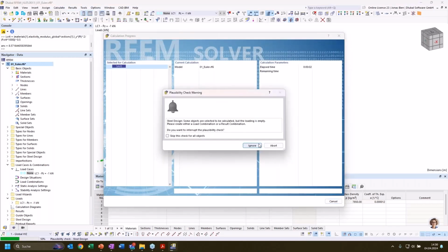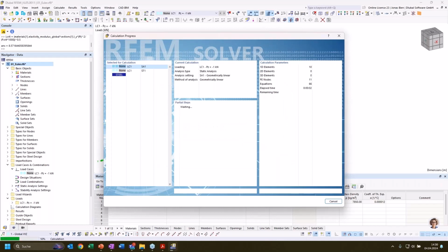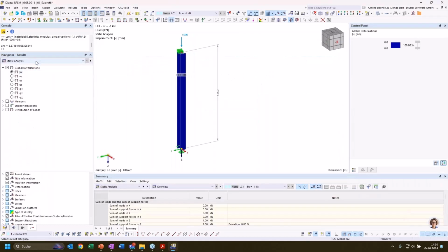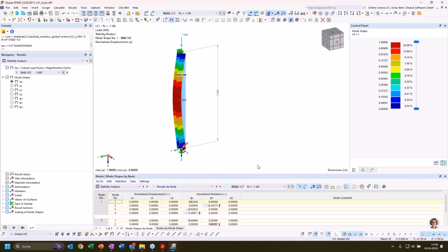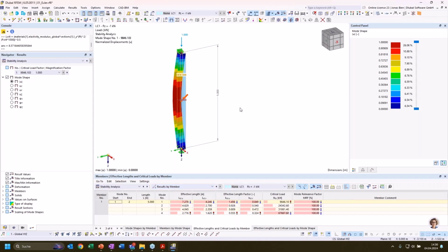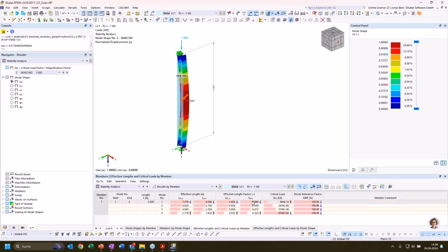Here it's not so obvious what the buckling length for our equivalent member check would be. Of course, we could look into textbooks that have these cases covered, but here we can also use the structural stability analysis to evaluate the effective buckling length factor. And as we expected, it is between 1 and 0.7.